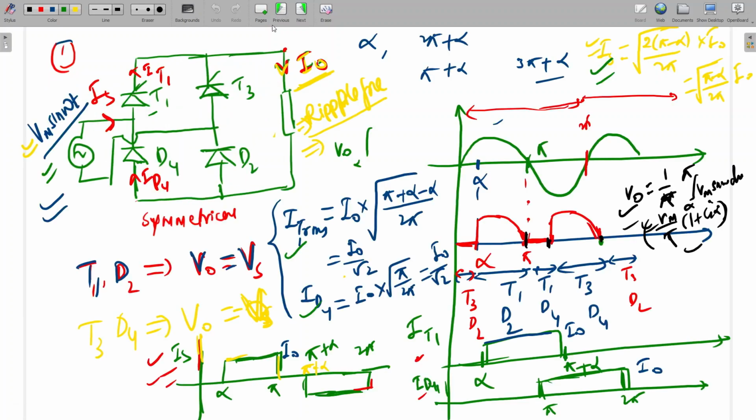In the previous question, if there is a freewheeling diode, what will happen? The same thing will happen, the freewheeling diode will take care, since the thyristor does not take care. The output voltage waveform will be the same, but the current waveform will change. Since the freewheeling diode conducts, the output voltage will still be 0. I will analyze whatever circuit you ask.